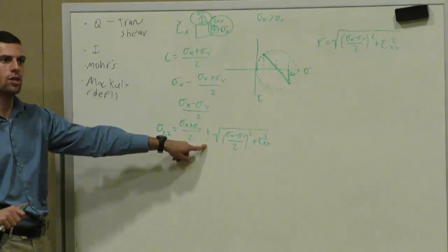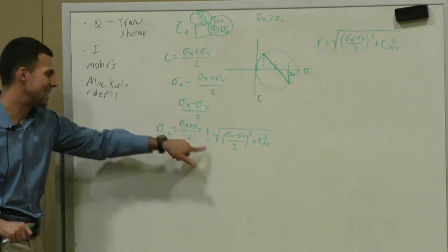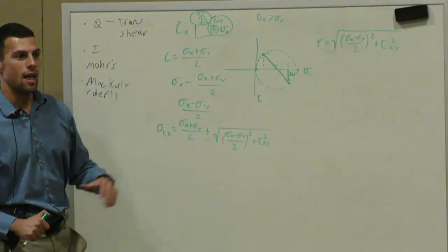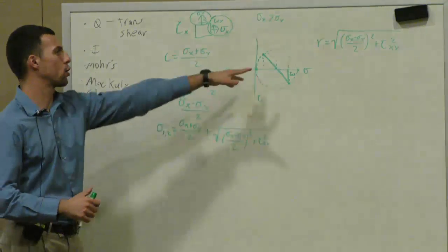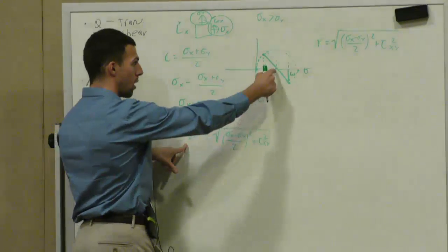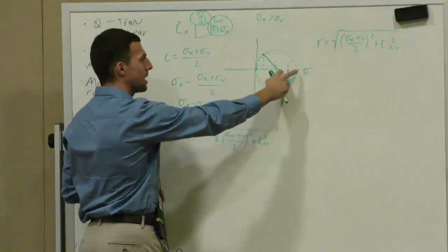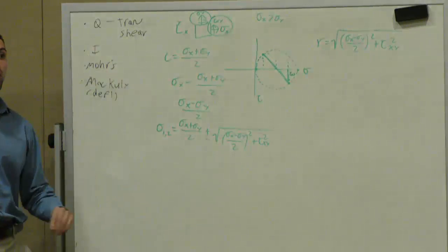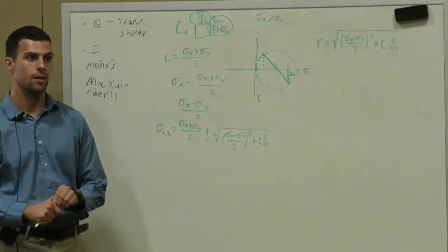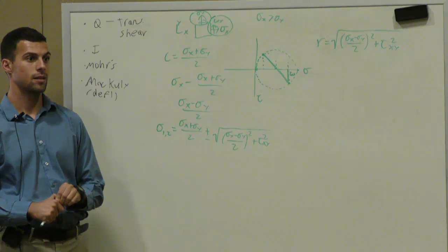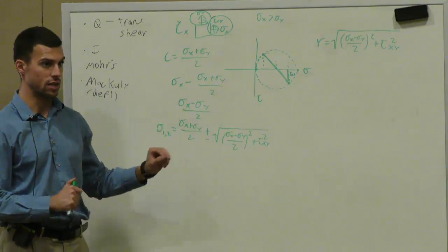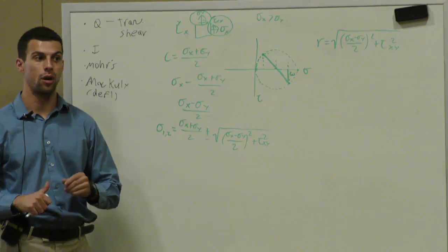Have we seen this equation somewhere before? This is the equation that the book gives you. This is, right? Now you can see how it graphically relates to Mohr's circle. It is literally center of the circle plus or minus the radius. Note, what else is the radius equal to? So these are the max and min normal stresses, right? What other point is important?